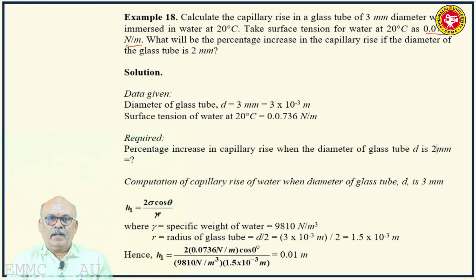Surface tension and capillarity are properties exhibited by liquids, only liquids. The liquid molecules have cohesion as well as adhesion. Cohesion is the intermolecular attraction between molecules of the liquid itself, whereas adhesion is the affinity shown by the liquid molecules towards the solid surface with which it comes in contact. Some liquids will wet the solid surface more, that means the affinity is more, the adhesion is more.